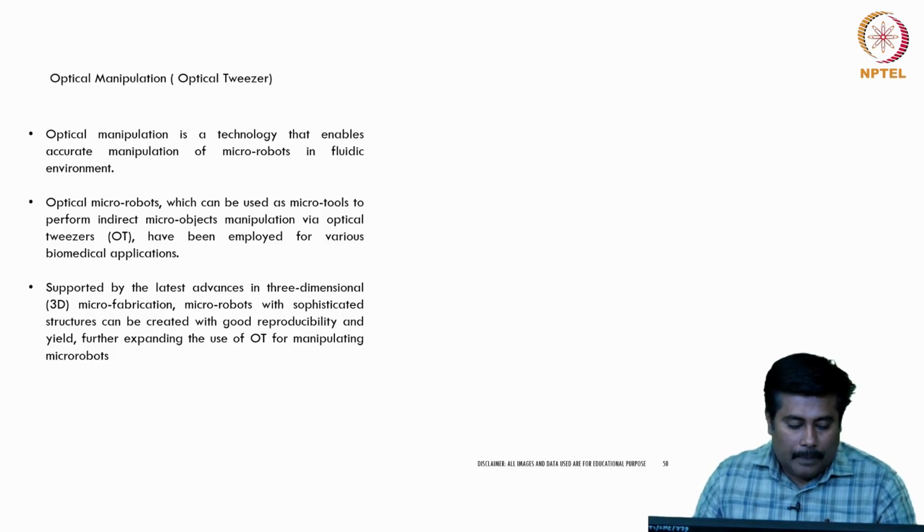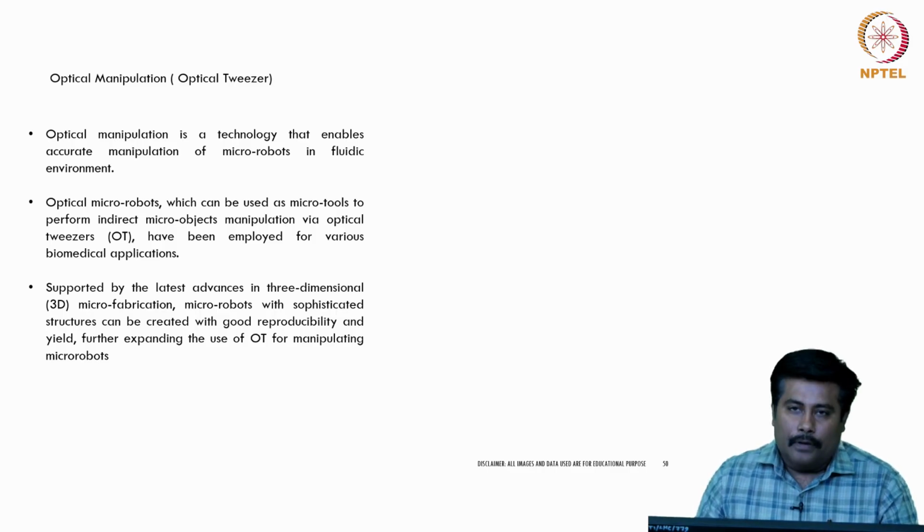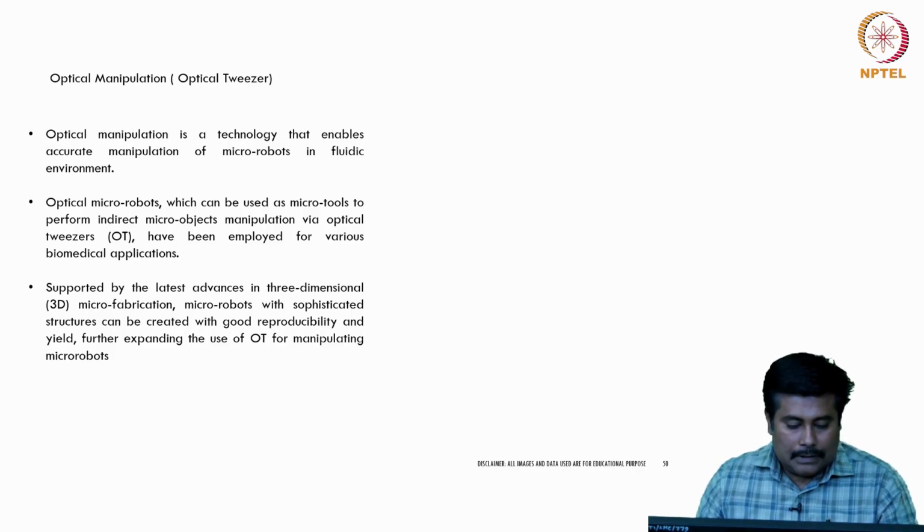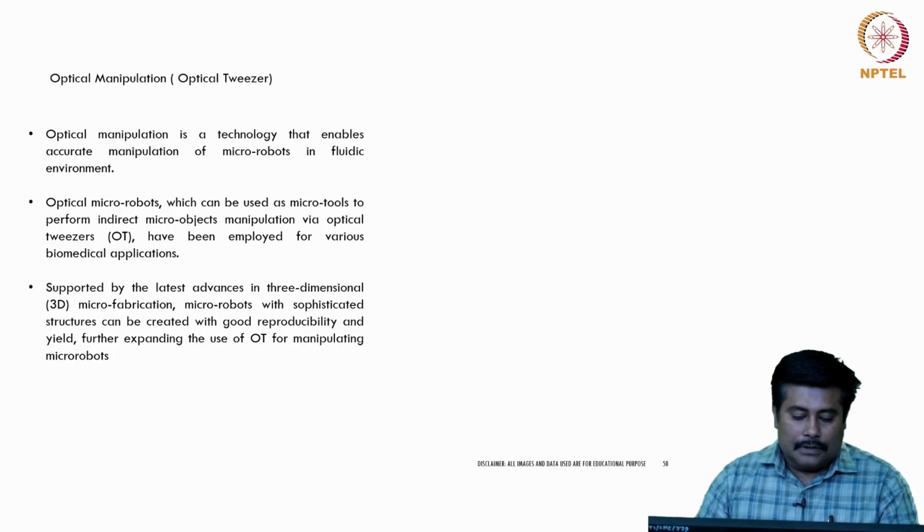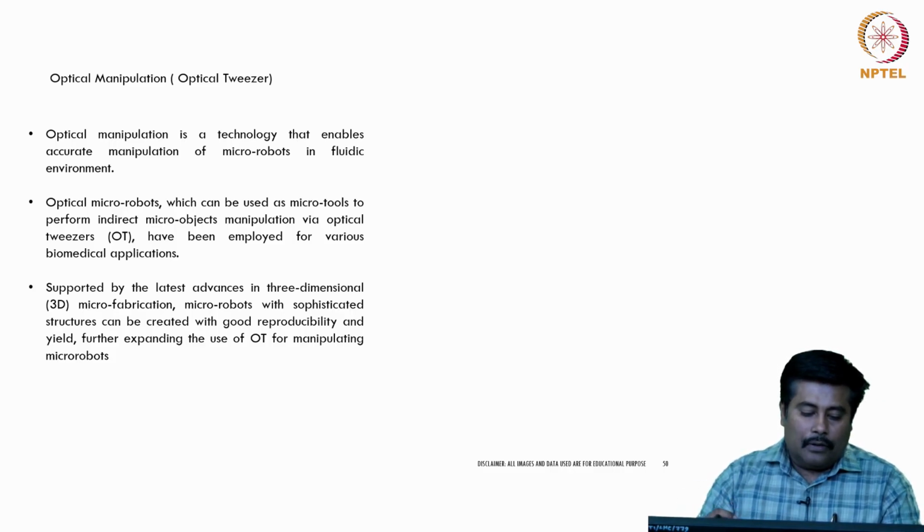So, these optical micro robots can be used as a kind of micro tool to perform indirect micro object manipulation via optical tweezers, and they have been employed for various biomedical applications. Supported by the latest advances in 3-dimensional microfabrication, micro robots with sophisticated structures can be created with good reproducibility and yield, further expanding the use of optical tweezers for manipulating micro robots.